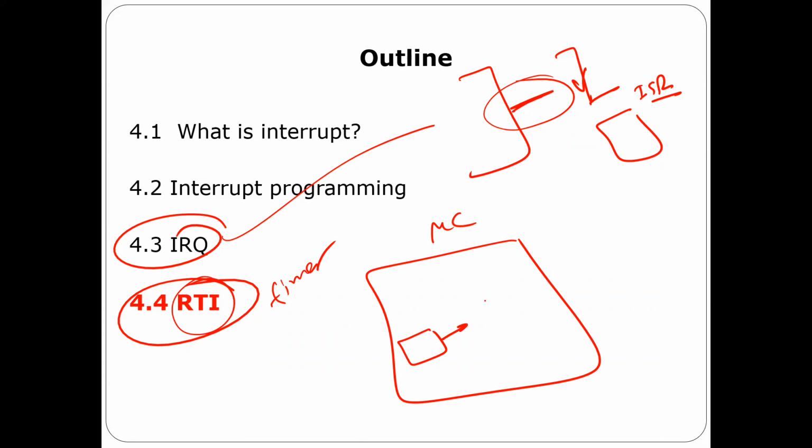This timer, and this is the CPU, right? So all you have to do is program the timer. There is no external pin. It's a timer, and you can program it. I'm gonna tell the timer, please, timer, interrupt me every 10 milliseconds, right?